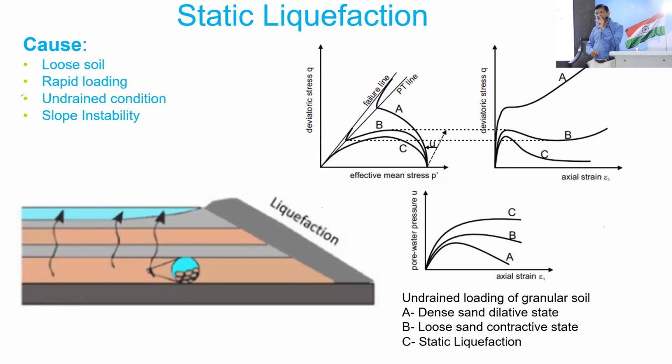So definitely at the time of failure, pore pressure was very high. So I back calculated that curve to see what the pore pressure was at the time of failure. So the pore pressure can increase very rapidly and also very high.